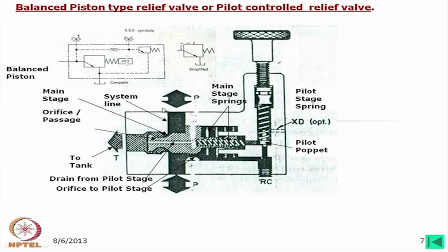Now, how is it being operated? The oil is going through this, it might be from this side or from the other side, that does not matter. When this oil goes through this orifice, it will come inside. Now, this one we may call a direct relief valve, but in fact this direct relief valve is called the pilot stage.